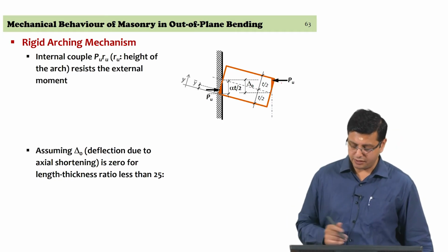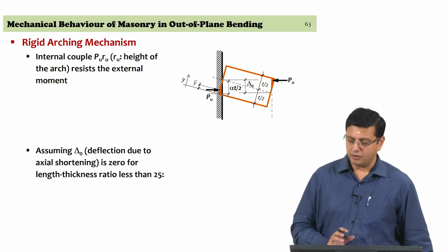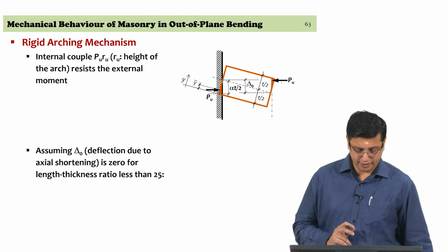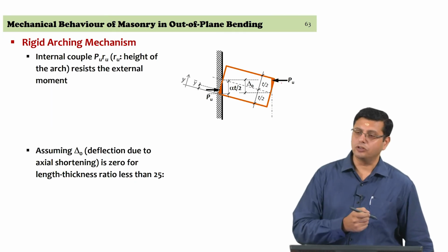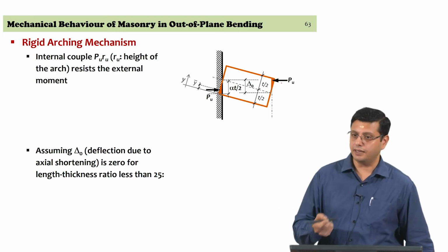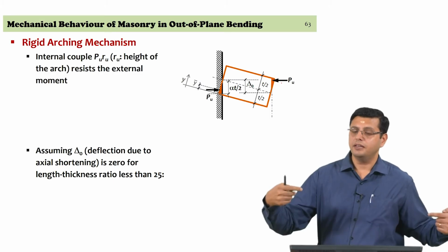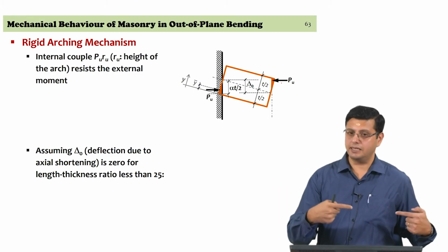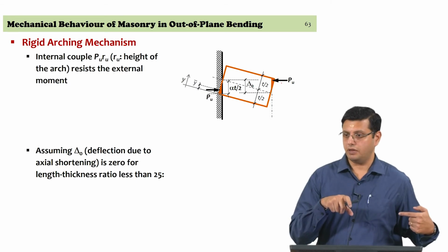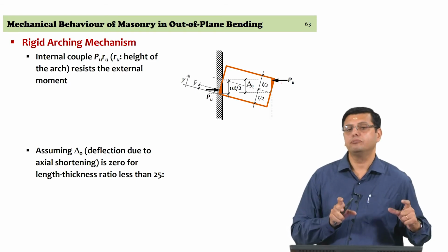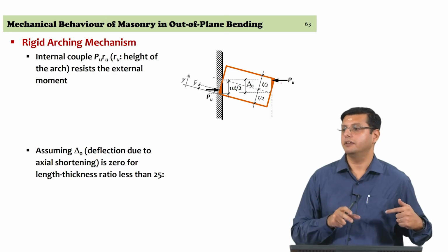one half of this problem and create a closed form solution to understand what is happening in this system. So, if you actually go back to the concept of the 3 hinged arch that is forming, the compression resultant Pu into the rise of the arch Ru is really the moment resistance that you are getting in the wall.